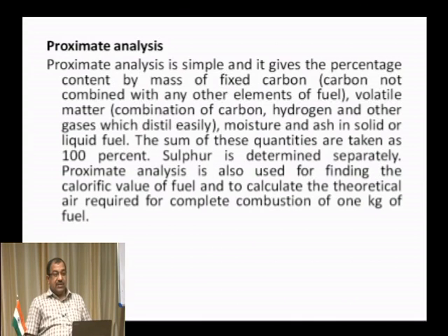In the previous case, we had neglected the moisture and volatile matter, whereas in this case they are considered. Okay. In this proximate analysis, sulphur is determined separately. Proximate analysis will also be used for finding the calorific value of fuel and to calculate the theoretical air required for complete combustion of 1 kg of fuel.